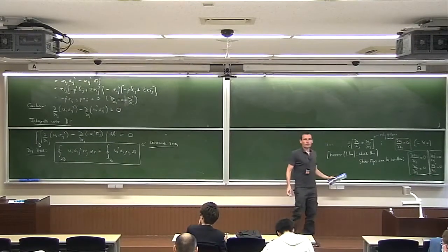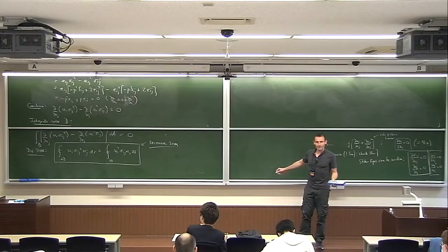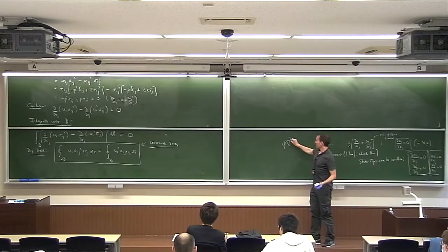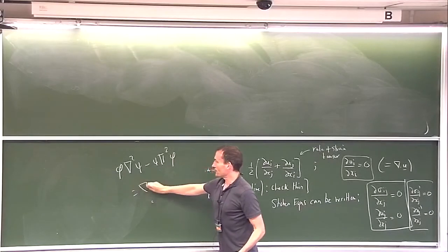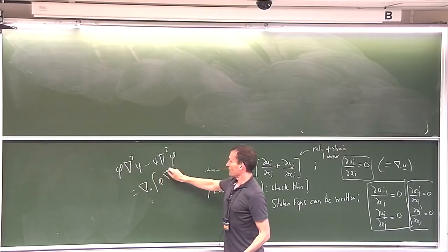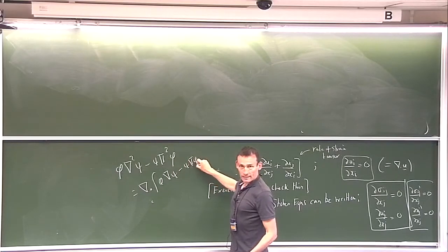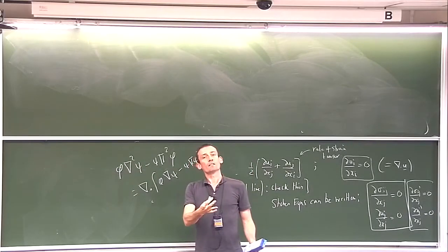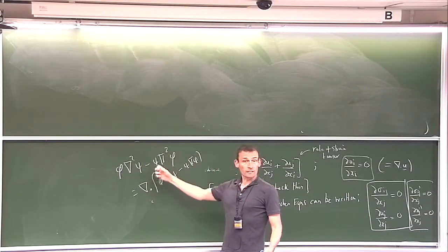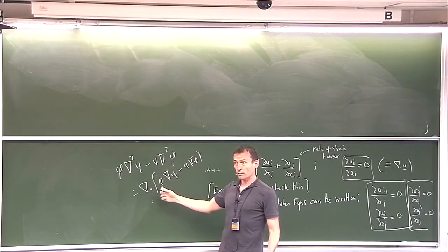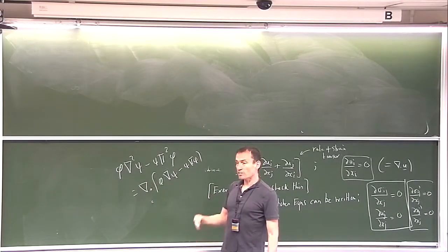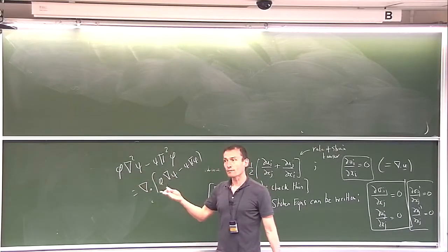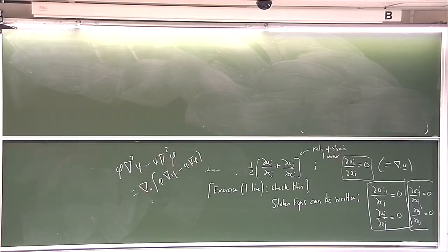Have you ever heard of Green's identities? Where you think about things like this. These kind of operators, which is the same as if these are harmonic fields. Really, I like to think of the reciprocal theorem as a biharmonic generalization of Green's identity. Because if you integrate Green's identity over the domain, you end up with a similar relationship between two harmonic fields in the domain. So I like to think of it as the biharmonic or Stokes flow analog of Green's identity.